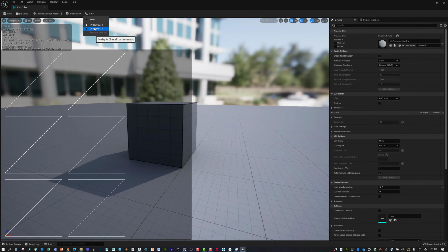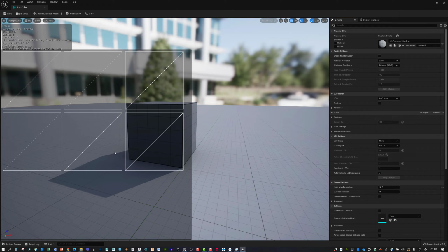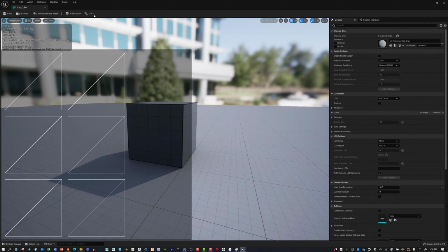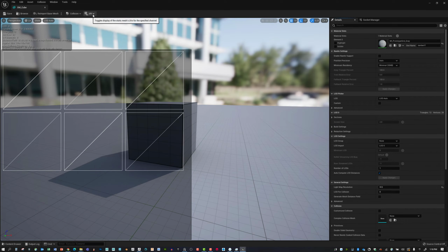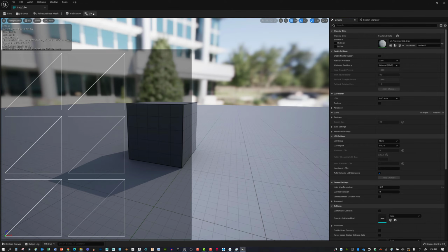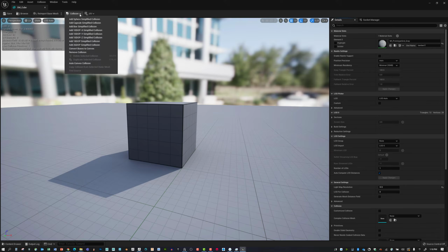If it has 2 UV channels, the second UV channel is for baking lighting information on there. You might be wondering, why are there 2 different channels? In programming terms, they always start with the number 0 to start counting. So that's why we have a UV channel 0, which is our first UV index, and then the second channel that we're using is 1. If you don't want to see that, you can click on none.